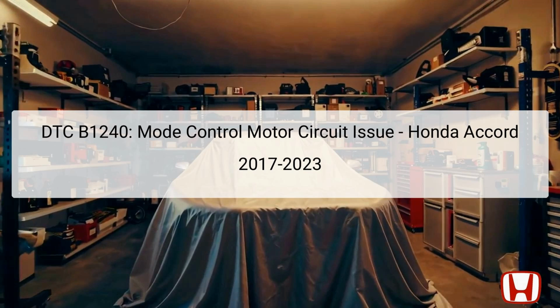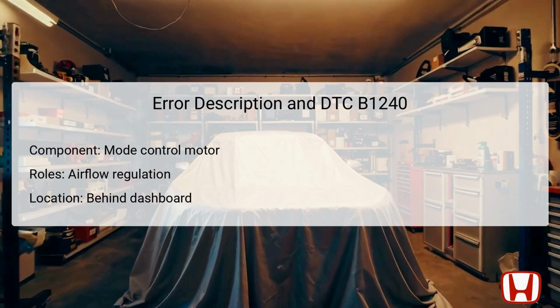Utilizing the Honda Diagnostic System, HDS, to troubleshoot will aid in pinpointing whether the issue stems from wiring, the motor, or other functional components. DTC B1240 indicates a malfunction related to the mode control motor circuit. This includes the motor itself, which is tasked with regulating air distribution within the Honda Accord's climate control system.